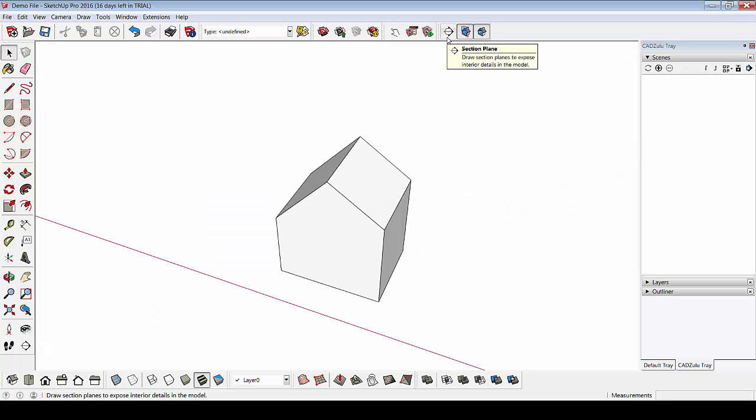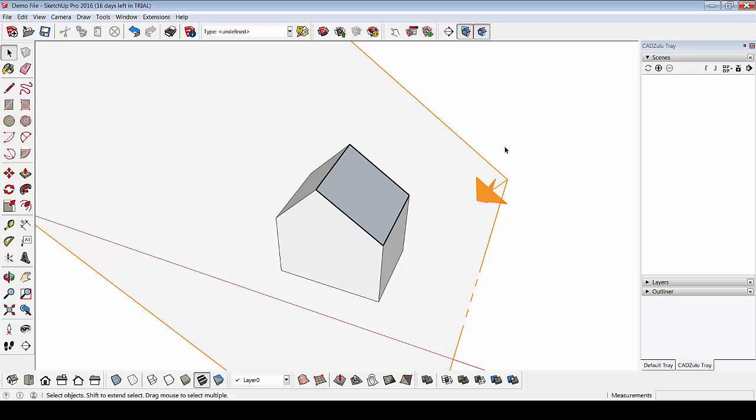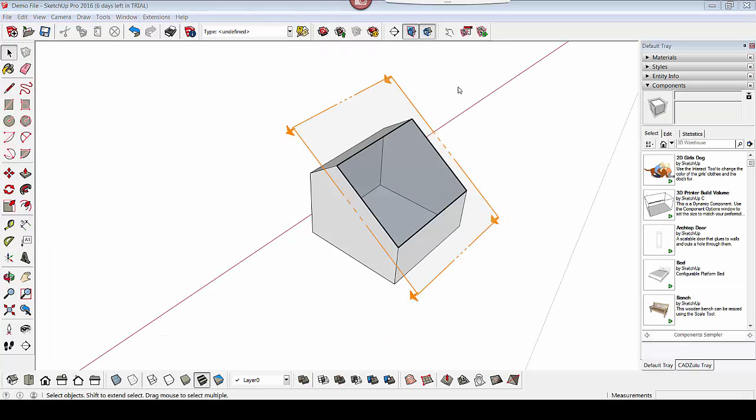SketchUp 2016 will now recognize intersection points with hidden section planes. So if you do apply, say, a section cut over there, if I just hold down Shift, it will keep that angle, so I can just slice through the model. And if I now click, say, on the line tool, you can see it actually snaps to these intersection points as well. In 2016, this will now also work when you hide the section plane, as you can see there.